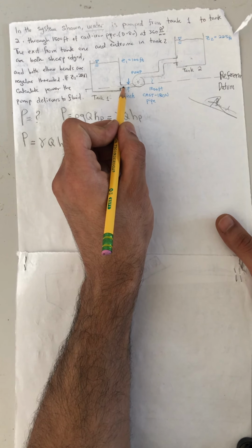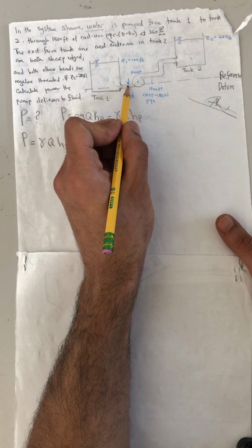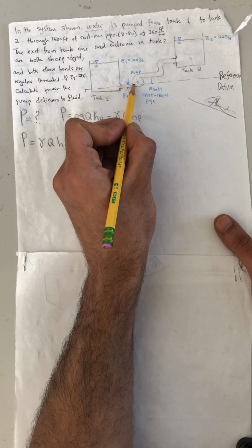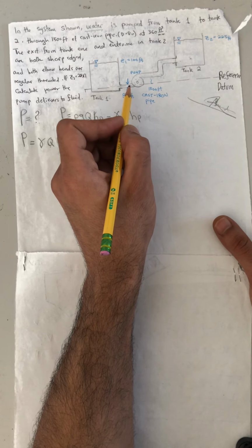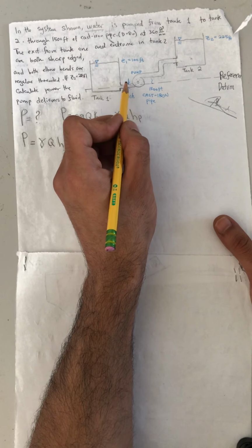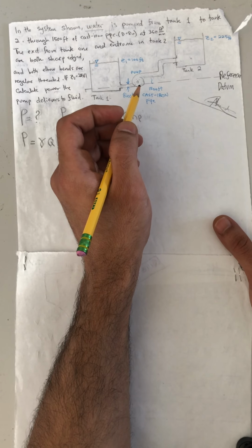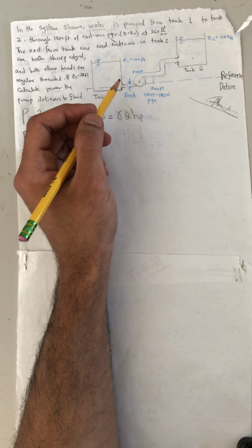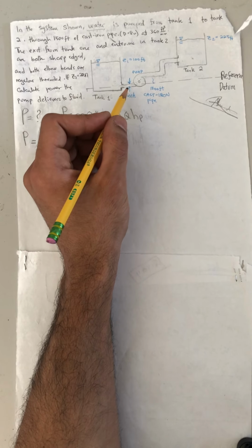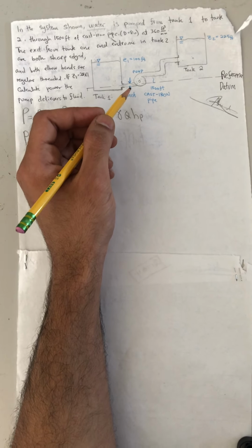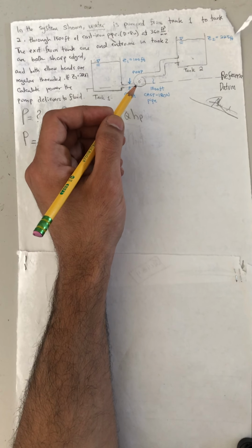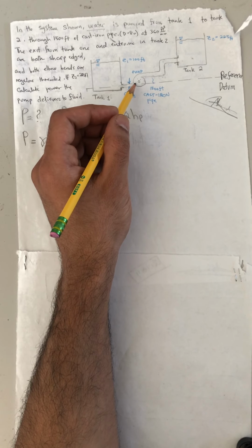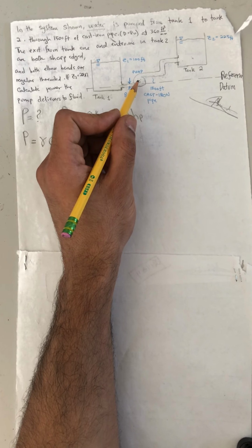So the velocity profile here is building up, reaches here, it is fully developed. It enters our centrifugal pump. Our centrifugal pump creates a centrifugal force. This centrifugal force creates an increase in the velocity of the fluid. This increase of the velocity of the fluid causes an increase in the kinetic energy, which is then transformed to pressure.